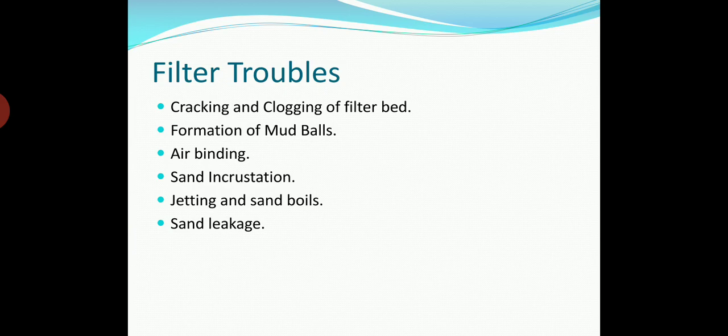So first you should know what is cracking and clogging of filter beds and why it is occurring. Surface clogging and cracking are usually caused by rapid accumulation of solids on the top surface of fine media. The compression and shrinkage of the soft gelatinous coating on sand grains tend to form cracks in the filter as the head loss increases. These cracks are more prominent near the wall junctions.